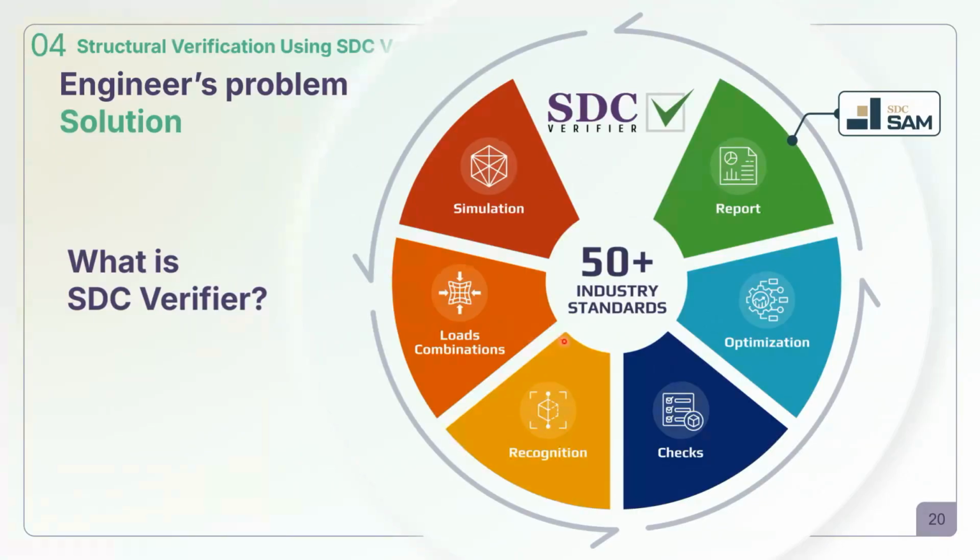because then it's obviously not the case. Another thing where SDC helps you is the recognition. So what does it mean? After your model is prepared, you get the stress results. The engineer actually needs to validate different structural parts, such as welds, panels for plate buckling, fatigue for welds, for non-welded parts. So the recognition allows you to automatically recognize these different structural parts out of your FEA model. Then checks, so the database of all the checks such as ABS, DNV checks, they are included inside SDC and can be used.